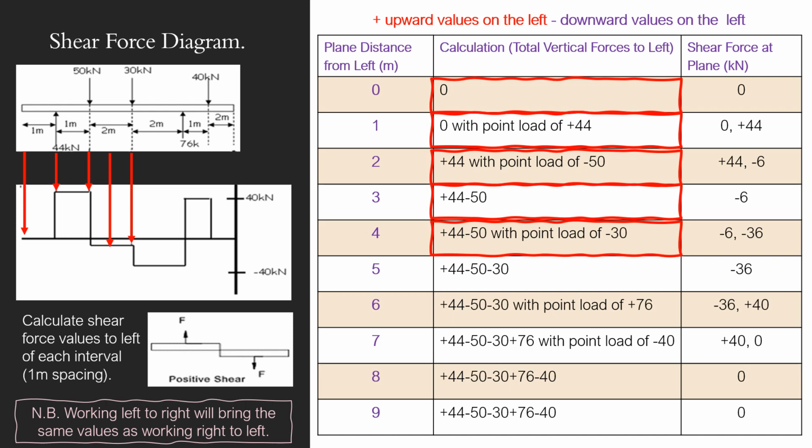And if it crosses the x-axis like it does here, this is a point to worry about. This is where it goes suddenly from one extreme to the other, positive to negative. It's pushing downwards, suddenly pushing upwards. So that is where you might find that the beam will have issues, and you've got to think about supporting it.